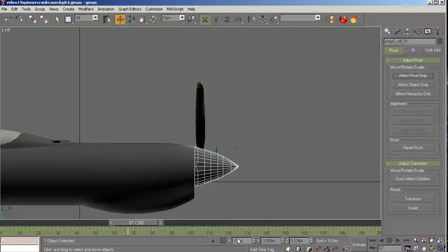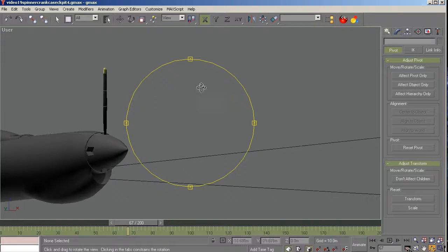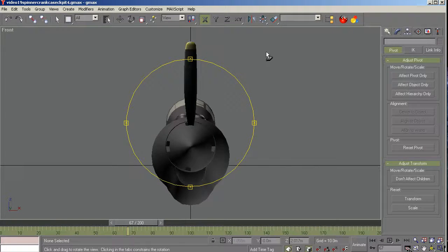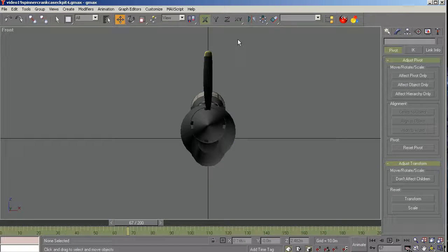Obviously it's going to be centered, but we wanted the 334, so after you have that, then you can go to the prop blade and make sure that the pivot on it is exactly at 0 on the X axis and 334 on the Y axis. I'm sorry, the Z axis. Okay, so once I have that, I know I can propagate this around the spinner, and it should do it perfectly. If I'm a good boy and don't mess up, we'll see how it works.